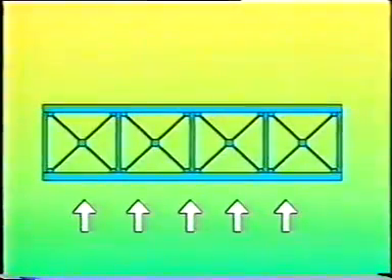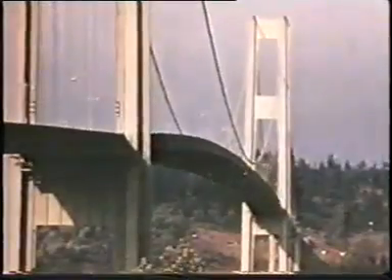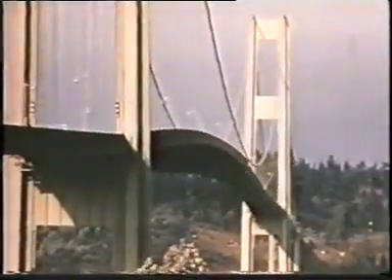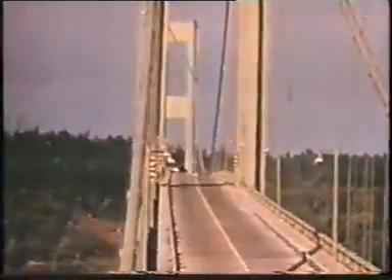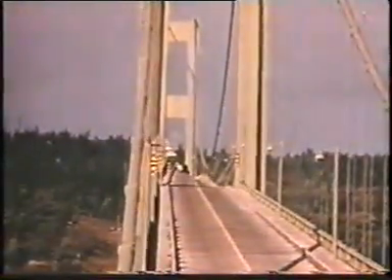Here, the stringers are omitted for reasons of clarity. The equally distributed wind loading is replaced by an equivalent set of concentrated loads acting on the joints of the wind bracing. These forces can now be transmitted to the supports. The wind bracing can best be observed in a railway bridge. The effect of wind loading can be rather dramatic. In this particular situation, even leading to destruction.